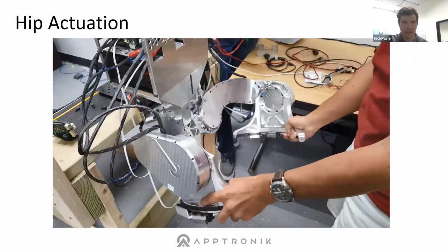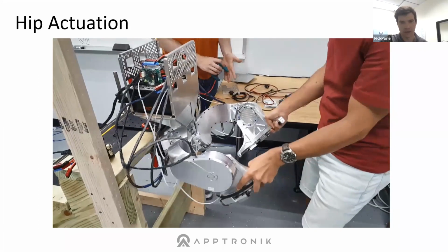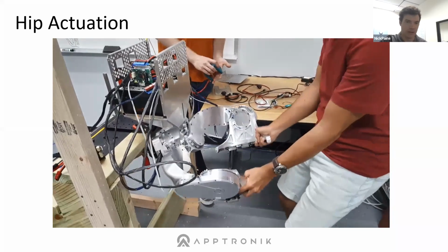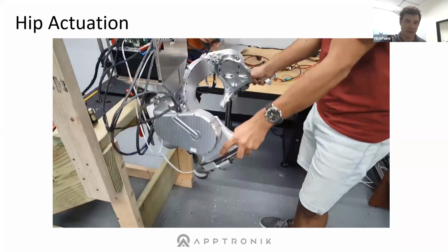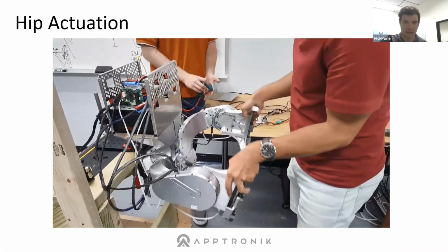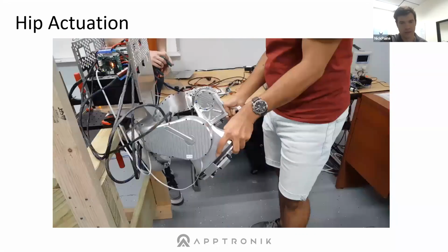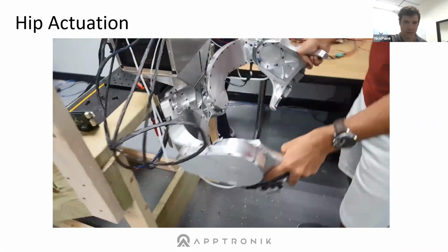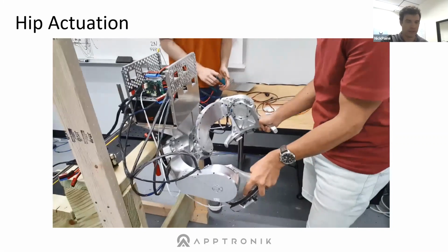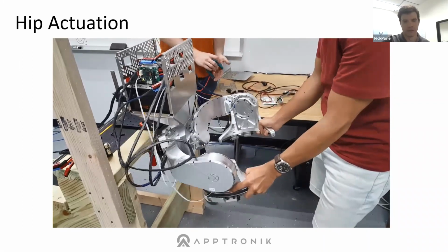So these next few videos kind of show some of the system design of this and some of the bring-up process that we used. This is an early prototype of the hip structure and the hip actuation. You can see the ABAD and the flexion extension dots here. These are rotary series elastic actuators. And you can see that the human's able to drive this around pretty easily. These are controlled in a pretty low impedance state. So it's pretty easy for the human to drive around.